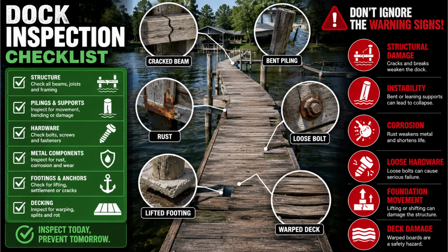After winter, the warning signs. Inspect your dock every spring. Look for uneven decking, leaning piles, new cracks, loose fasteners, separated joints, warped frames, rust, broken welds. Early repairs are usually far less expensive than waiting for a major failure.